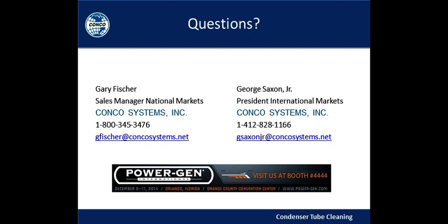This is Gary again. That's an excellent question. You have to make sure that the cleaners you buy are of high quality, first and foremost. The type of cleaners we use are carbon steel, and they have some tension to them so that they can fit into the tubes tightly.